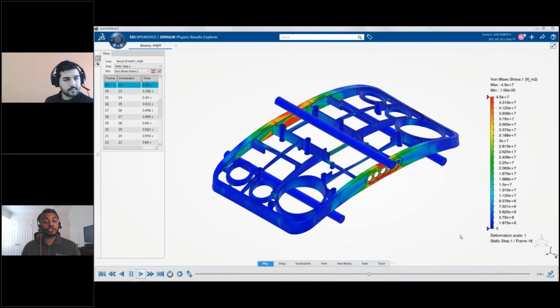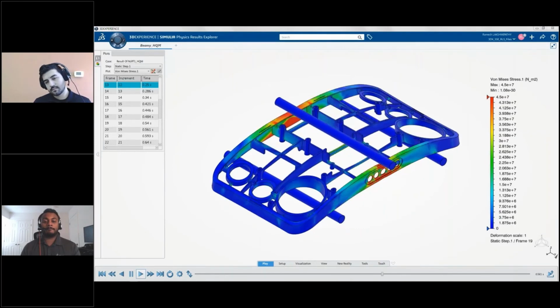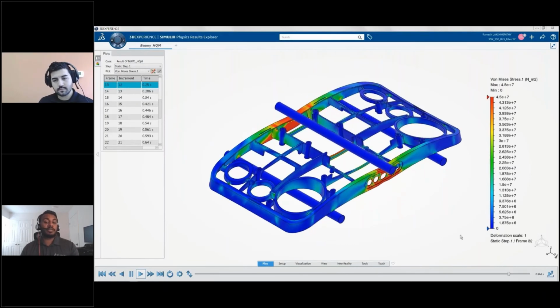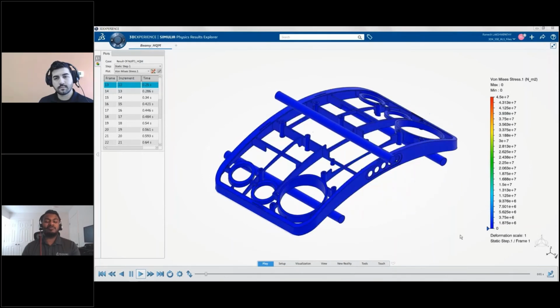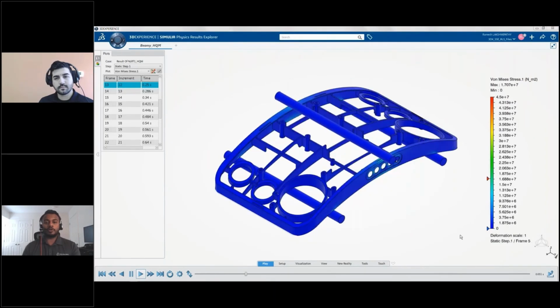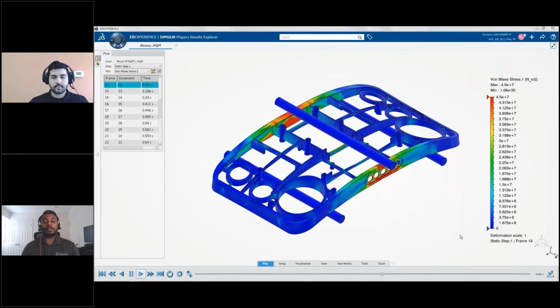We can also see from a stress perspective, right? We want to make sure that we are not stressing the plastic. We can actually see what that looks like. Now, one thing, Julio, I wanted to bring up is that we tried to run this in SolidWorks simulation before we ran it on the platform. SolidWorks simulation was actually very difficult to solve a simulation like this. SolidWorks simulation does have a nonlinear solver, and it is a really good fit for a lot of applications. But a simulation like this, with a bilinear material which has some snapback effect, was a struggle to solve in SolidWorks simulation.